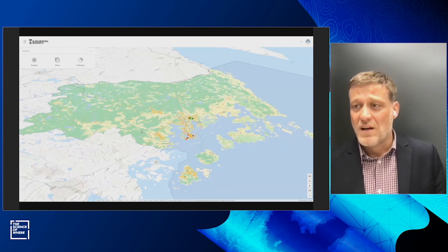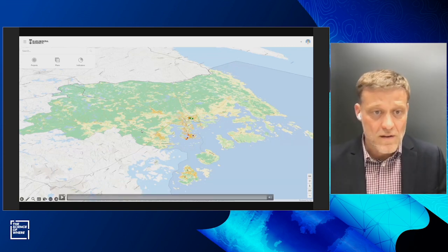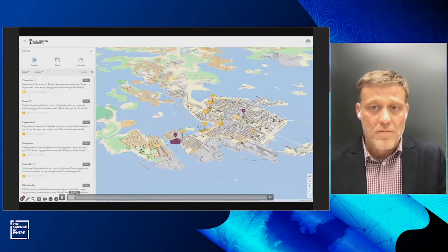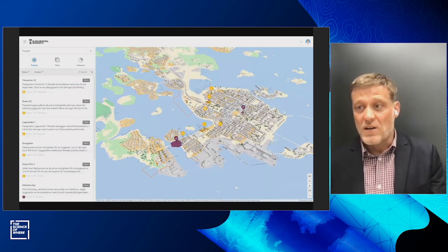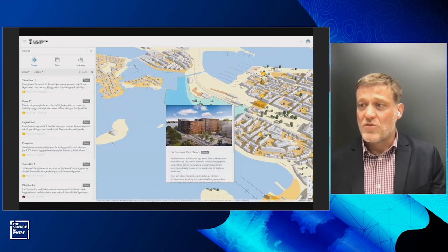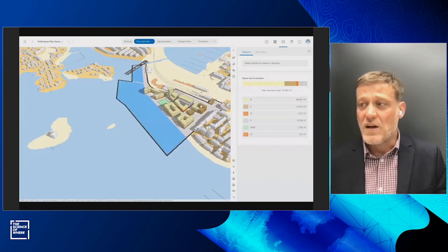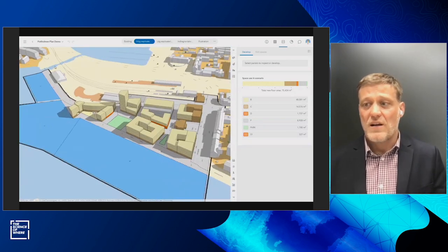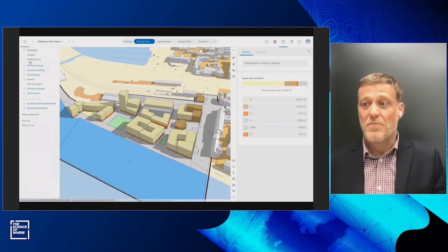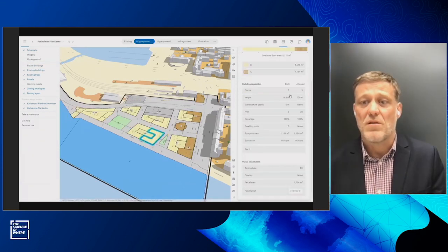And in this example, it shows the municipality of Karlskrona in Sweden. It shows you that in Urban, for example, which is an online tool, you can create certain scenarios for different planning situations in the context of the 3D city model, right? And changes can be made to underlying policy zones, such as maximum building heights, for example.